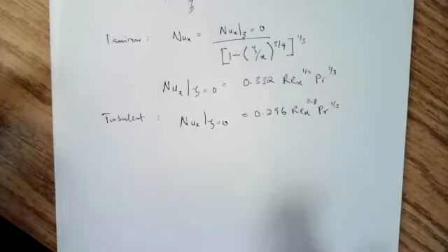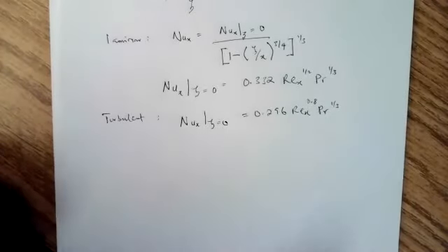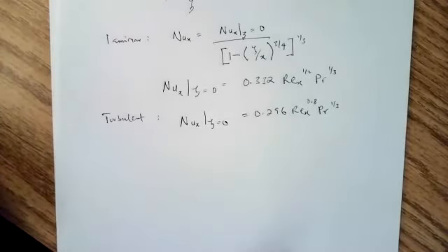Whatever analysis you do on your system determines if you think it's a flat plate with unheated starting length or a uniformly heated flat plate. It always comes down to that. So if you are able to do this analysis and come up with the right conclusion, then you'll be modeling the accurate system. Okay.